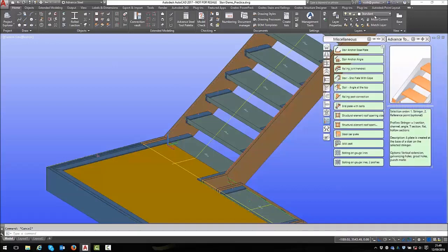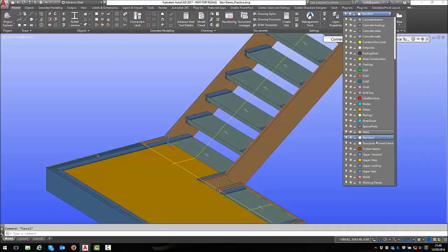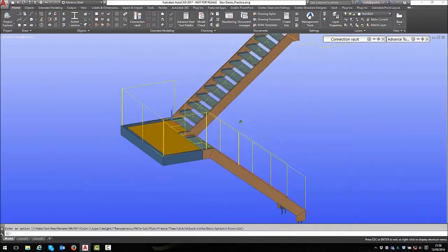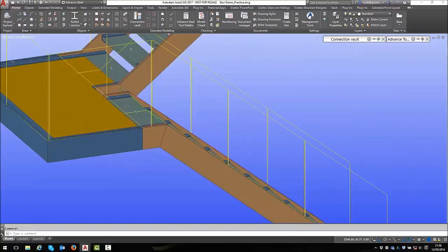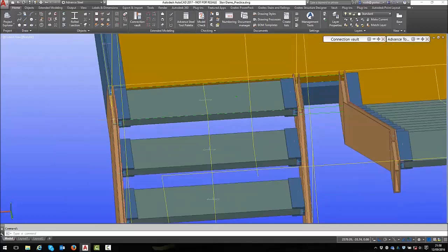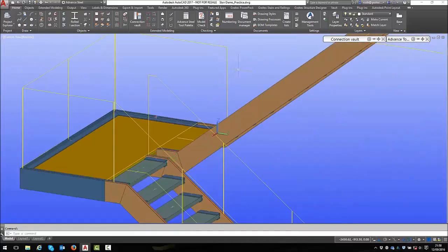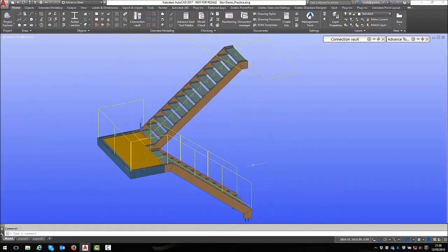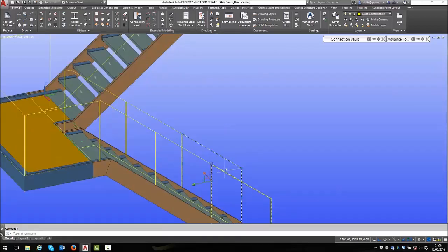What I'm going to do, I've actually got some glass. Here we are, upper glass. But I've actually got some glass construction. Here it is. Okay. So what I've done basically, I've taken a line from center inside my glass channel. I've taken some lines here. I've given it the necessary offset. So it's 1130 as it happens here. And obviously it's a little bit less on the stairs. And I put some glass panels in. I say glass panels, the outline for the glass panels.